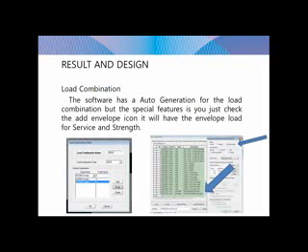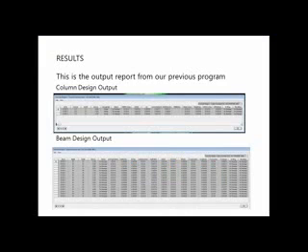Load combination. The software has the auto generation for the load combination, but the special feature is just check the add envelope icon. It will have an envelope load for service and strength. This is an example of a result output from our previous program.